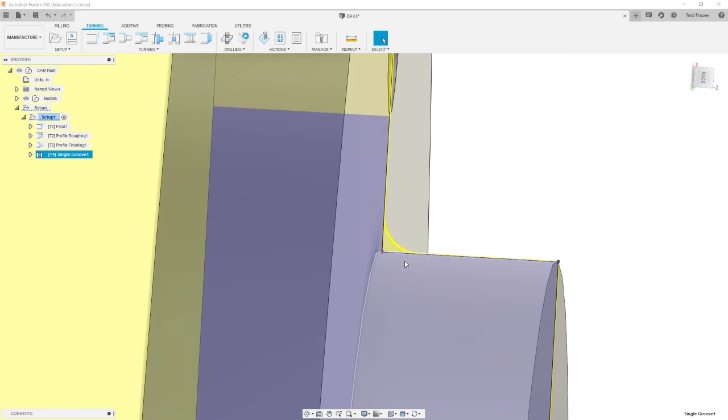Now it's actually going to leave a really small fillet here. The best way to handle this if we were actually machining these parts would be to put a corresponding radius on the inside of the cylinder, break the edge so that that matches nicely.